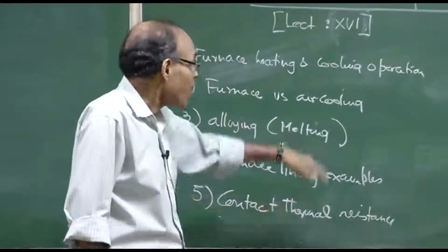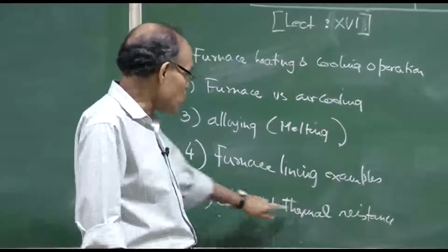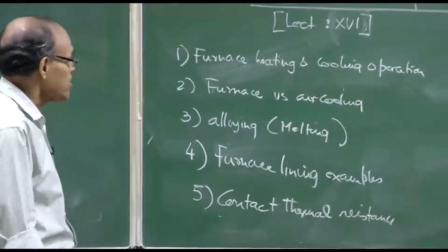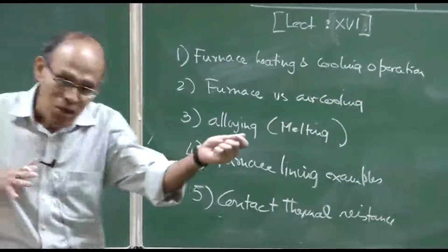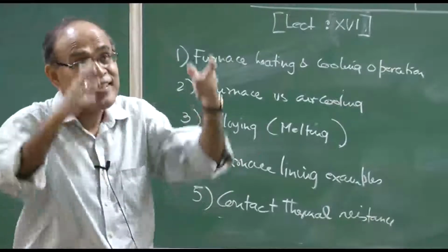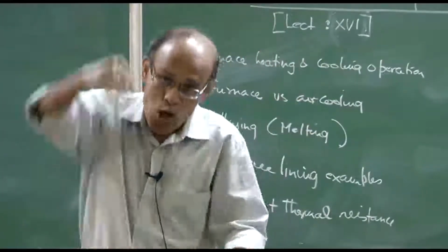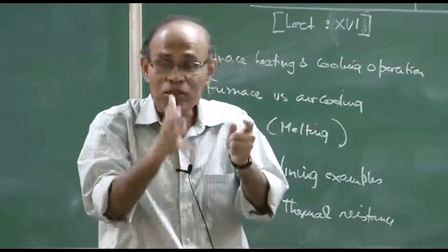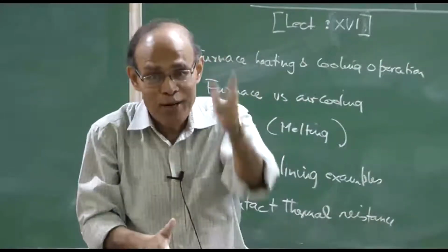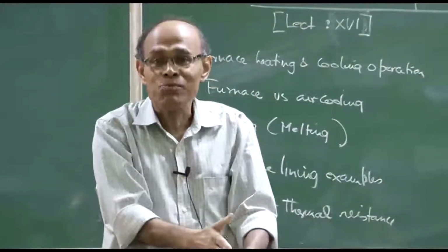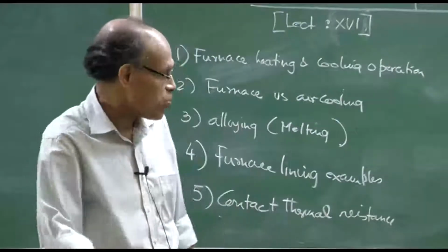And we will also see that our fundamental knowledge will allow us to determine the contact thermal resistances, maybe between a solid and a liquid, okay, as it is in the case of a ladle shroud, for example, through which molten metal flows, and the molten metal does not necessarily completely wet the shroud or the refractory surface, because they often contain graphites and so on and so forth.